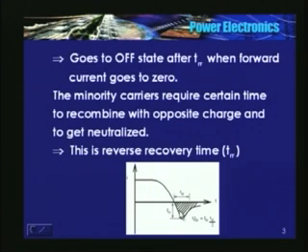The area of this shaded part is nothing but IRR, the peak, into TRR divided by 2, the area of the triangle.